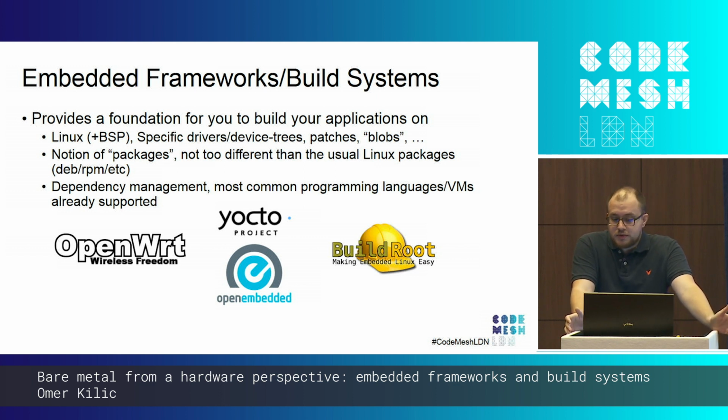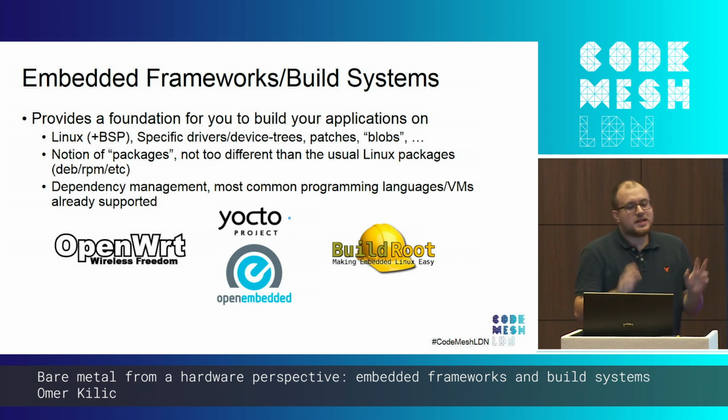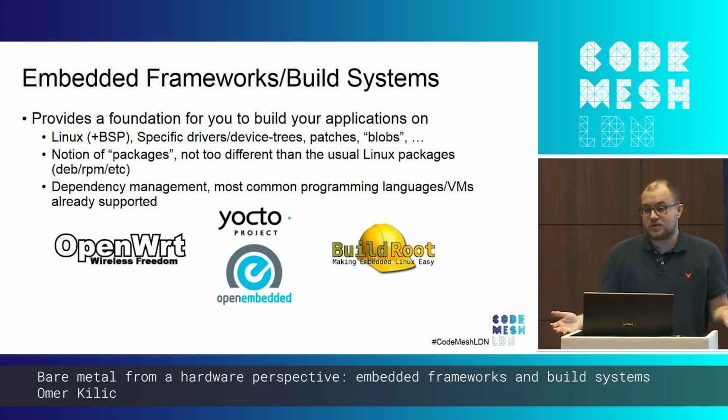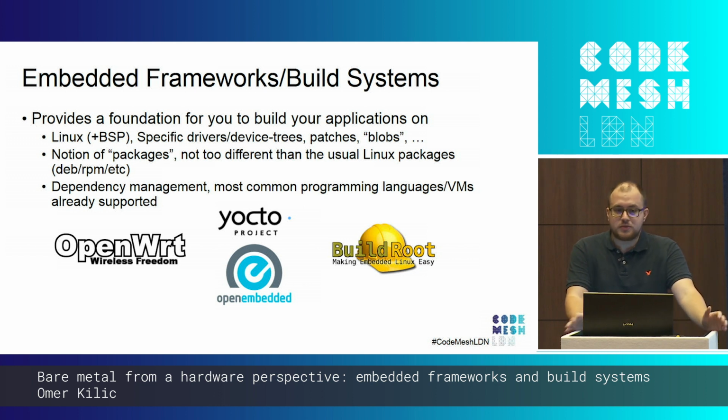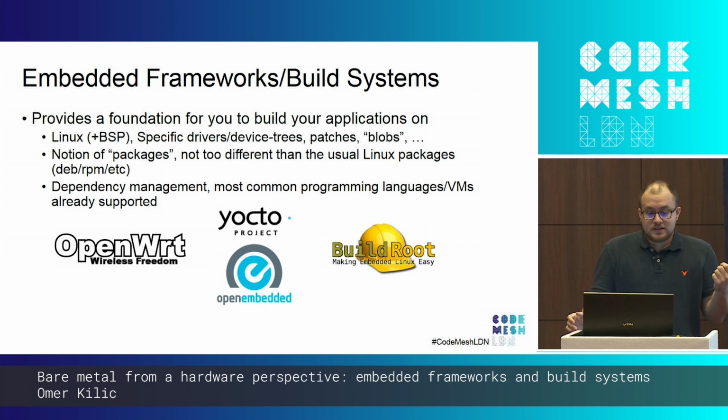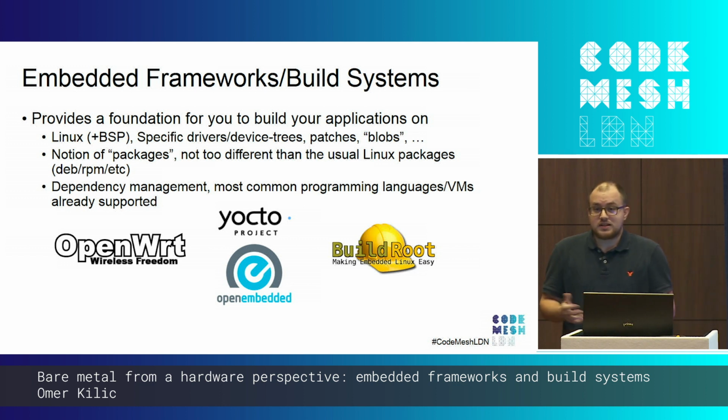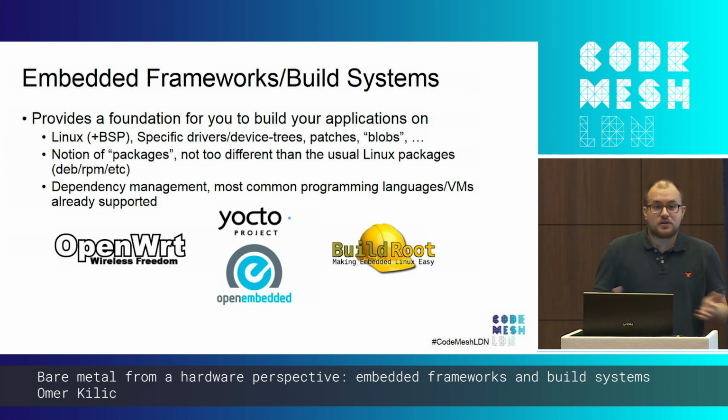But the problem generally is that you'll find slimmed down versions of the libraries that you're using if you're resource constrained. And also, depending on the architecture you're running, that can potentially cause issues. An example of this is that we're running Erlang on a device with 8 megabytes of flash, and on MIPS, which is not necessarily the architecture that Erlang is mostly run on.